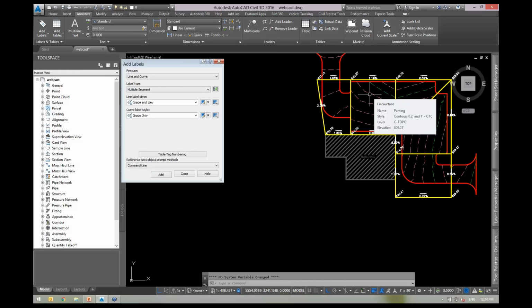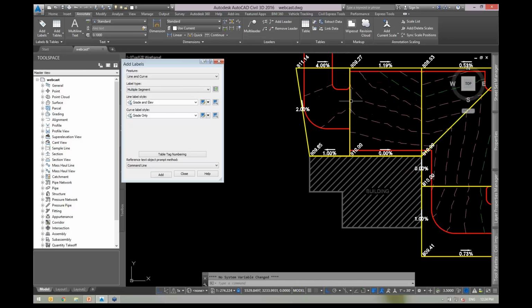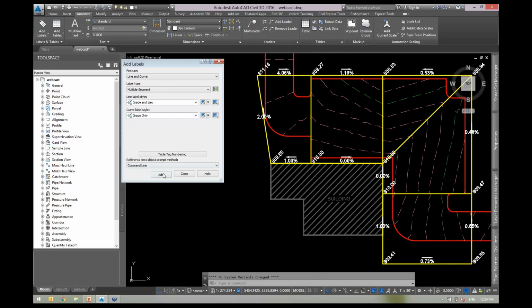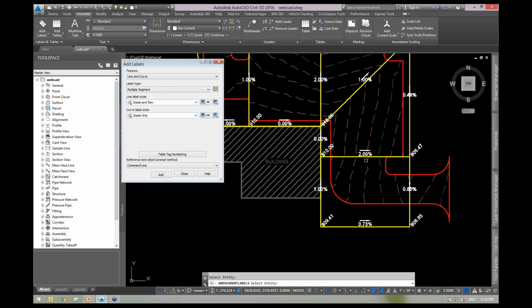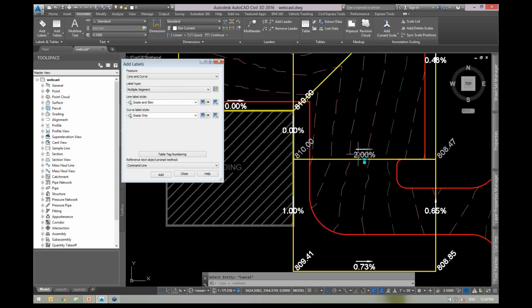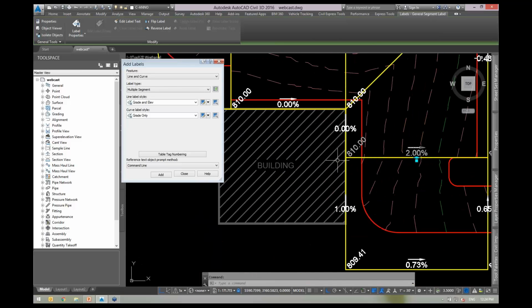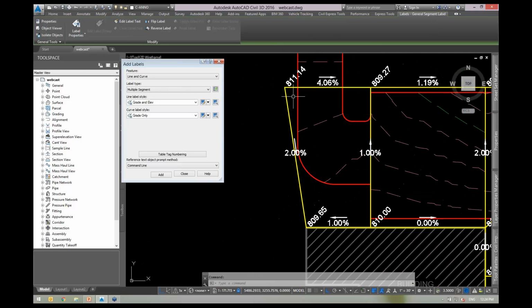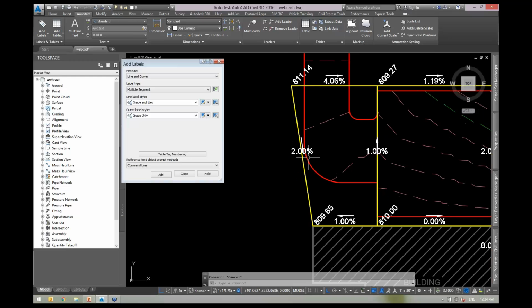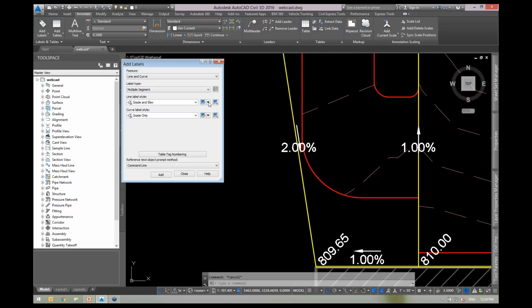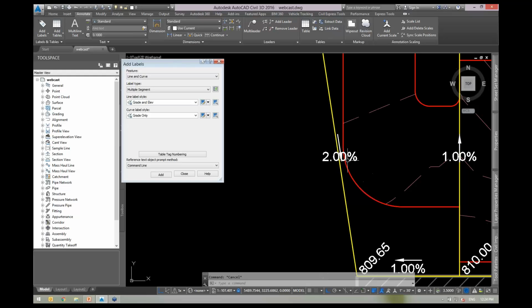I want to just boom, add it all on there at once, and then we can move forward. So for example, I can add them right here as well. These are feature lines running across the middle here. And you can't even quite tell, but it's the same label style, and it's putting those elevation labels at the same spot. But they're right on top of the other one. So it behaves like it's just one single piece of text there. Works out pretty nice.